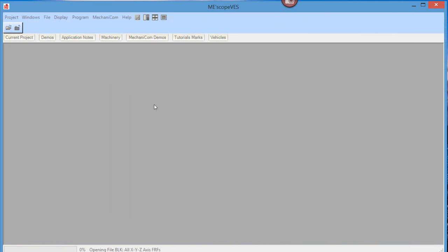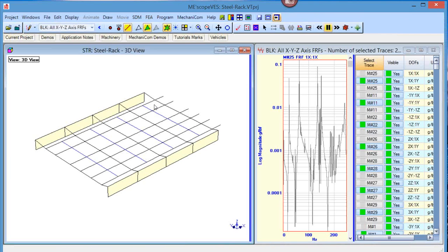And so many times if there's a noisy machine or an objectionable noise, it's because a resonance is being excited somewhere in a machine or in a structure, in a piping system. Depends on what it is. We call that structure-borne noise. So resonances are audible many times, and then many times they're not. But the machine may just wear out too quickly or break, castings break, and weldments come apart because of too much vibration.